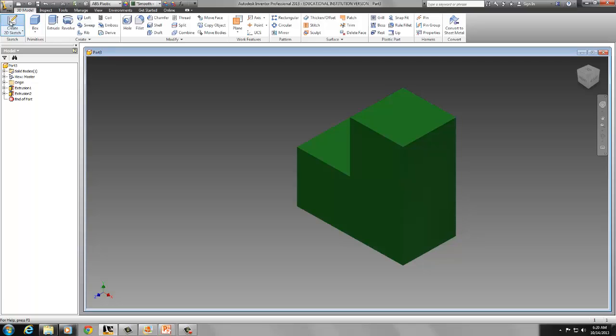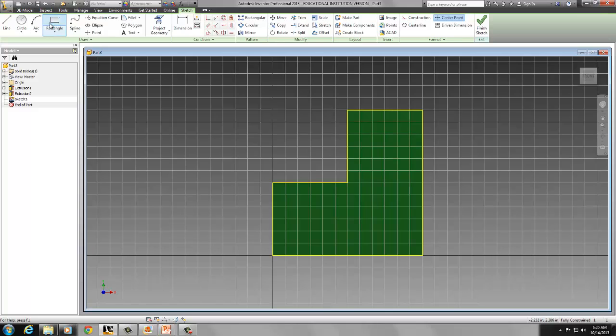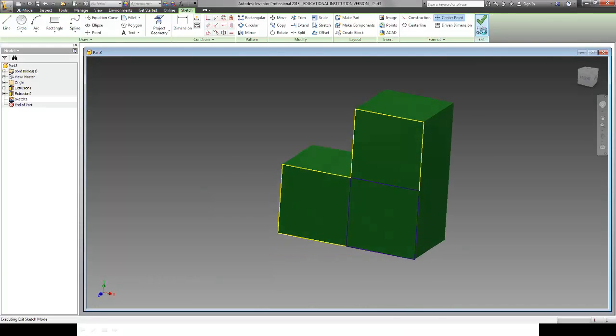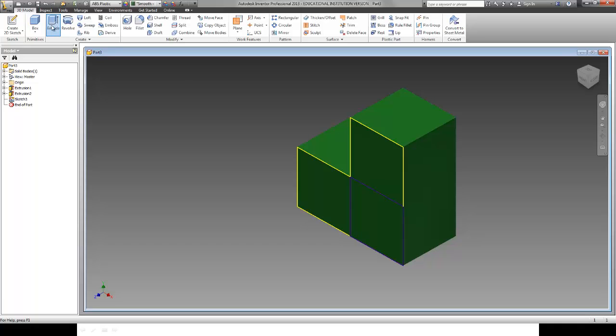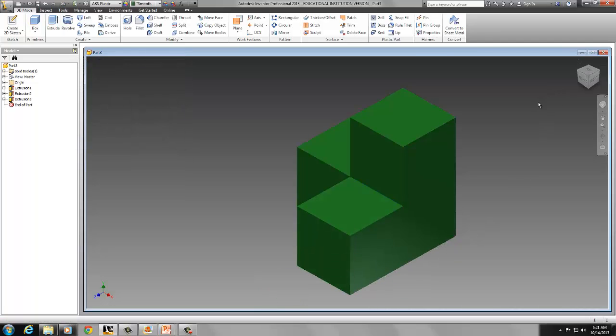What I'm going to do is make another 2D sketch on this surface, and I'm going to take the rectangle, come in, green dot, makes a constraint, come up here, green dot, makes another constraint. You can see we have 0.75, 0.75. Left click, right click, OK. Finish sketch. Extrude. Choose the selection. It's 0.75. I'm going to accept it. And now this is my part.